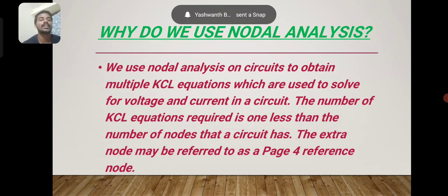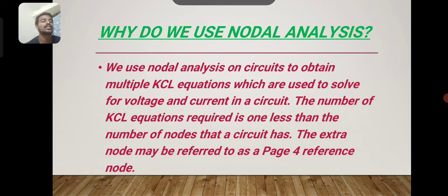Why do we use nodal analysis? We use nodal analysis on a circuit to obtain multiple KCL equations, which are used to solve for voltage and current. The number of KCL equations required is one less than the number of nodes that a circuit has. The extra node may be referred to as the reference node.